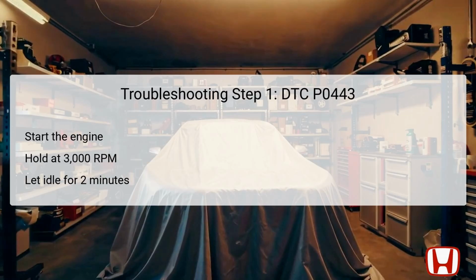The first troubleshooting step for addressing DTC P0443 involves starting the engine and holding the speed at 3,000 RPM without load until the radiator fan activates, which indicates that the cooling system is engaged. Once the fan kicks in, allow the engine to idle for an additional 2 minutes.